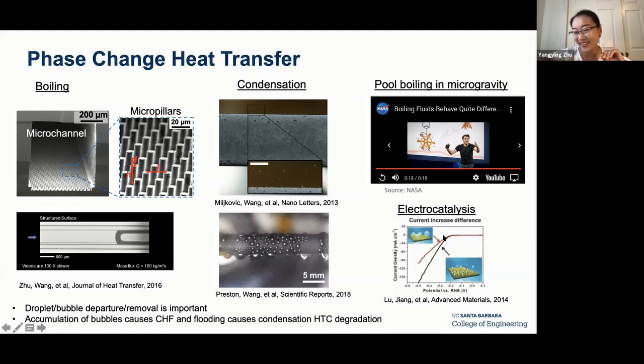how you treat your substrate is really important. If you have a substrate that is a little bit hydrophobic, so that any gas bubbles produced get stuck to the surface, you see much worse performance. Versus in the bottom right figure, if you have a super hydrophilic substrate where any gas bubble you generate, while still very tiny, is able to depart the surface, you see much better performance.